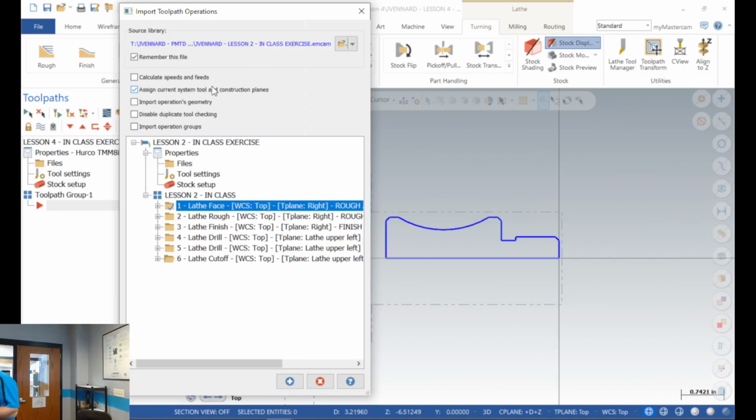There's been times where I've had assembly drawings or assembly models given to me, and they come into Mastercam and I don't go in and move the parts all around. I just create new planes. I know for a fact there's been times I've had mill and lathe parts come in the same assembly model where I'll just shut the level off for whatever the mill part is, and then I'll create a new plane on the front nose of the lathe part, and then I'll program that lathe part wherever it's at in the graphics window, by creating new planes.